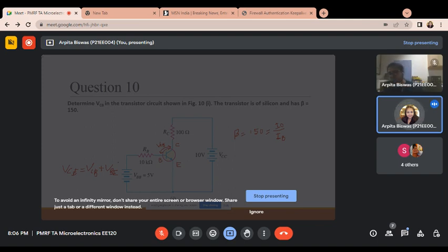And for the other students also, please try to solve, and then I will explain here how to. Tarun and Samuel, at least try. Take some time and at least think how to solve. Here the VCC is given, RC value is given, RB value is given, also the input voltage, the VBB is given, and we have to find out the VCB. And here I have written one equation: VCE equal to VCB plus VBE.